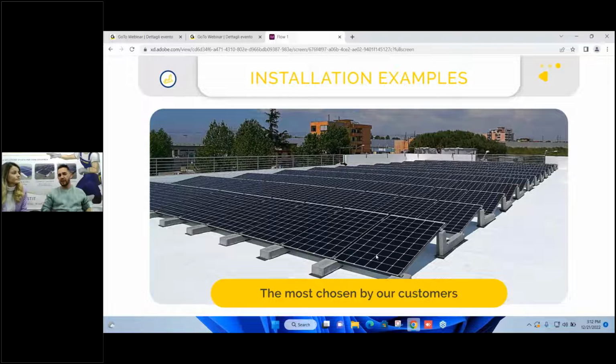But if you remember, we've done several installations on industrial roofs which are even inclined, right? Yeah, exactly. There are roofs with a slope of 0 to 5 degrees, let's say, going up to 7, even up to 10. We've done some installations. Of course, those need to be checked by our technical department, but yes, you can use it. Of course, we go with low inclination there, so we don't want to risk the ballast falling from the roof. So everything is checked by our technical team.